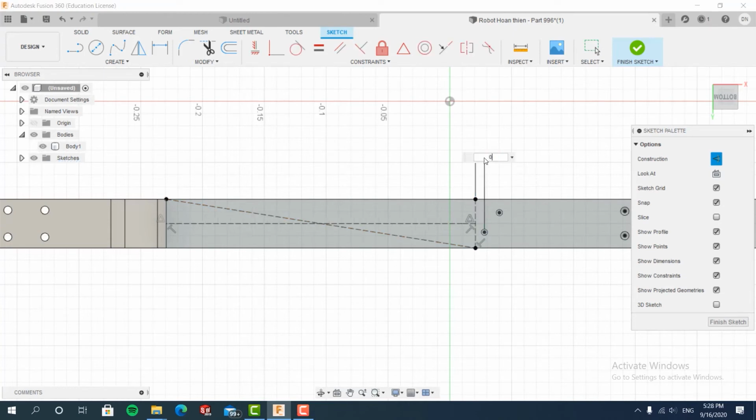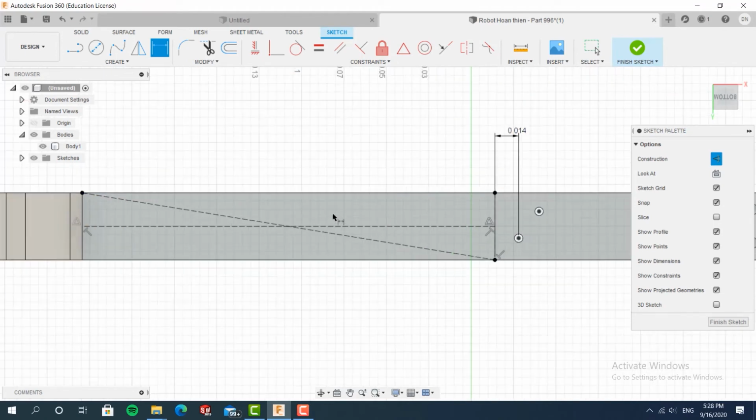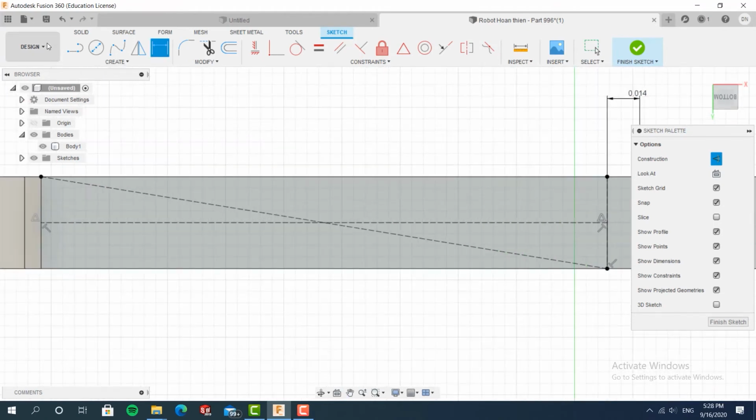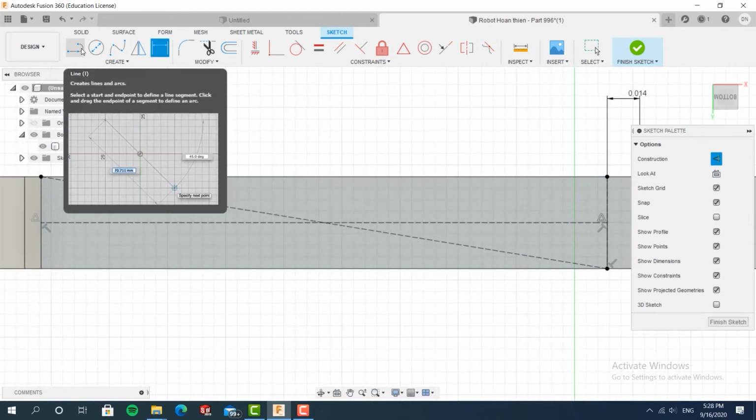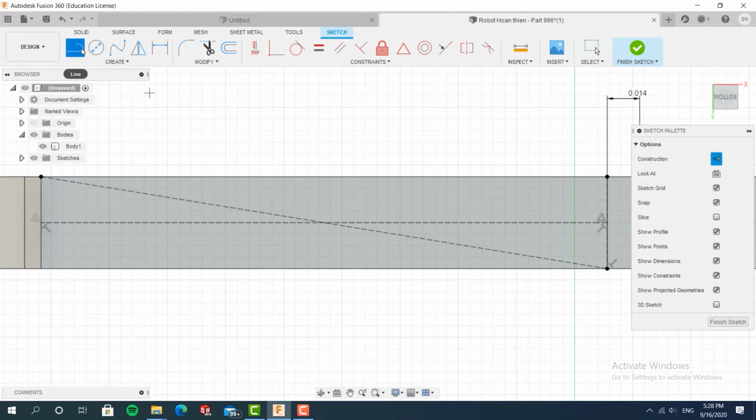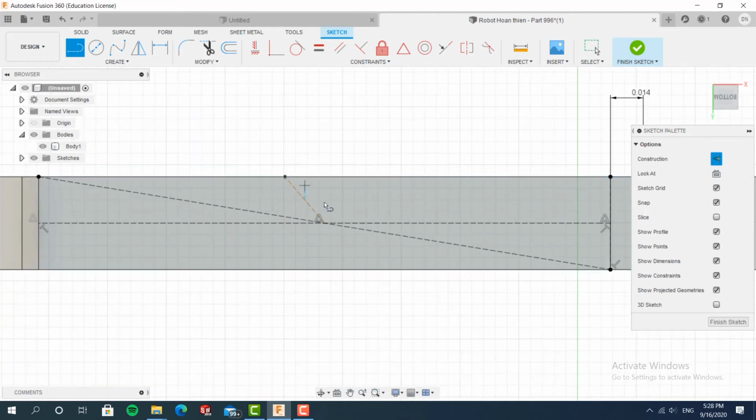Why triangles? First, cutting out triangles will make it a lot lighter than just cutting out circles. You can get out a lot more from corners. It's just a lot lighter. Another thing is that cutting out triangles makes it pretty strong, unlike cutting out circles. If you're cutting out until you have the same volume with circles and with triangles, the triangles are going to be a lot stronger.